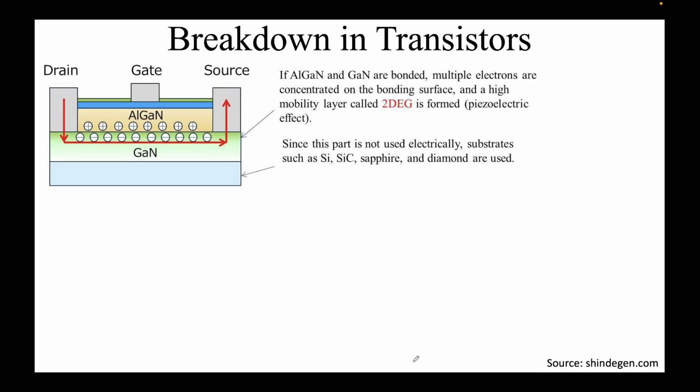Okay. So today's session, if you went through the lecture, I believe you did, the professor is talking about something called micro-fabrication. And before micro-fabrication, a few things about transistors and their applications, right? Among the transistors, we have already talked about, for instance, the drain current. We also talked about it when we discussed MOSFET, that the insulator is perfect, and we saw that the gate current is ideally 0, correct? Here we'll try to elaborate that those assumptions are not entirely true. Ideally they should be, but we live in a real world.